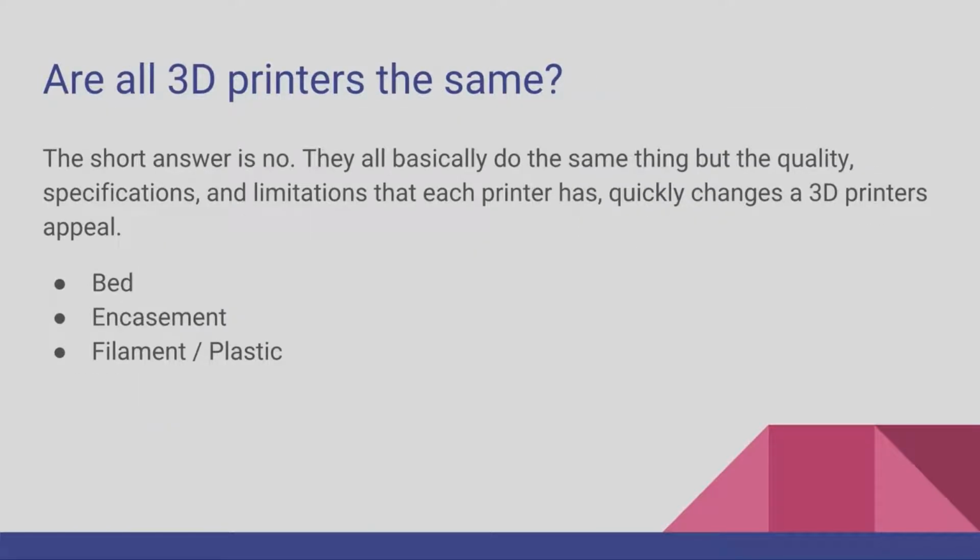Now, are all 3D printers the same? The short answer is no. When you're looking into getting a 3D printer, some things that you should consider is, does it have a heated bed? So like previously mentioned, some plastics require the bed to be at a certain temperature in order to print, or to have a nice finish.